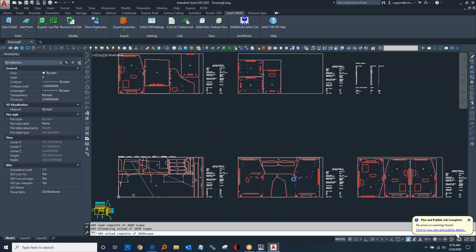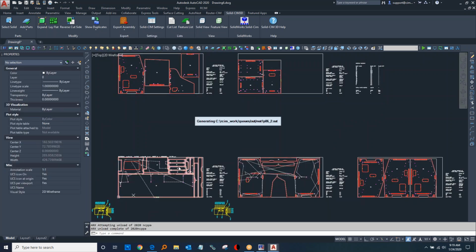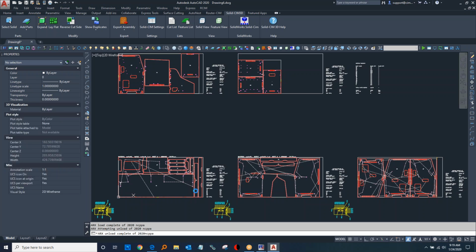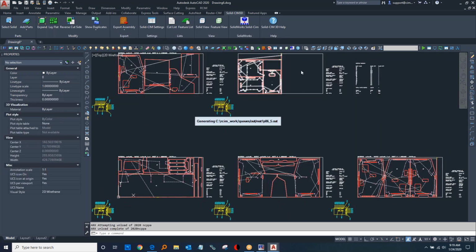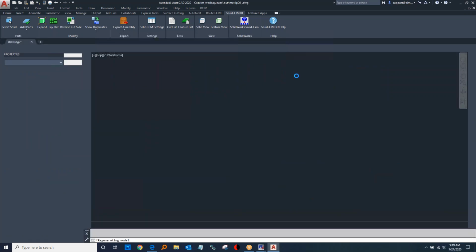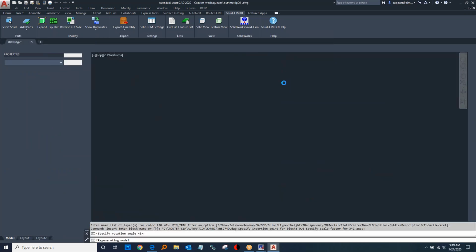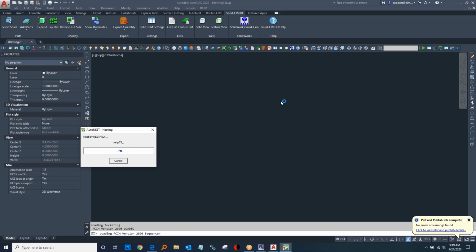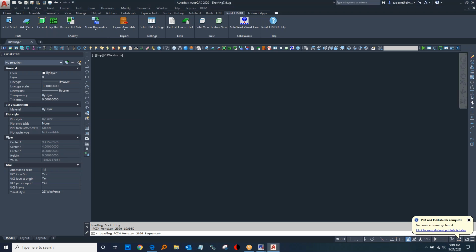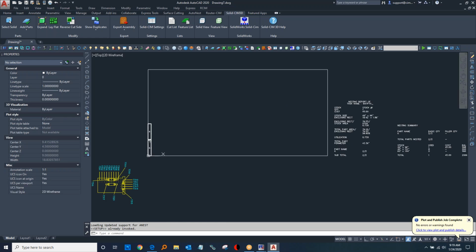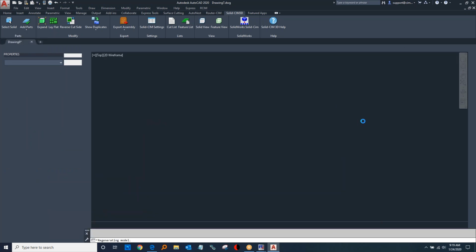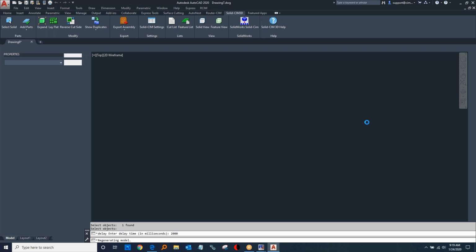So each of these different materials is processing. It prints these out to whatever printer you have connected. It can also print to a PDF file, so you can get both a hard copy and an electronic copy. Scrap cutting takes over, so we'll cut 2 pieces of scrap, and it can save these pieces for next time. So we've got automatic scrap management, and then after all the nests are completed, we'll have labels for all the parts. We'll have reporting summaries for all the parts, and all that information is stored inside of a folder with the same name as the original assembly.